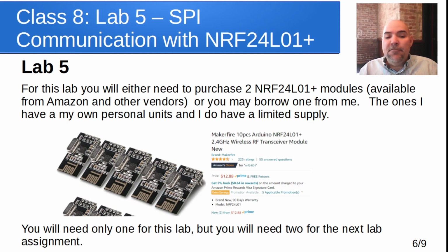Well, somebody made it convenient and made a nice module out of it that includes this PCB antenna on it, so you don't have to connect an antenna. You just plug the right signals into this module. And you're going to use those DuPont style cables, little cables. You can plug a female end into this and a male end into the Arduino. And this just has these 8 pins. For this lab, we only really need to connect 7 of them. And we'll talk about that in a second.